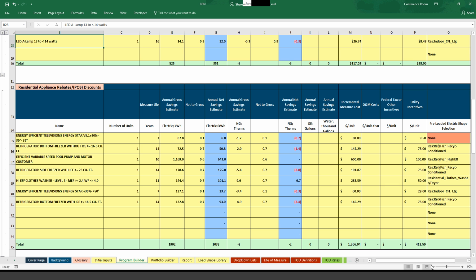We had to choose some, and so those are the ones that we settled upon, in part because a number of places do actually borrow values from the DEER, and that's the Database of Energy Efficiency Resources, I think, is what DEER stands for. A lot of states do have what's called a TRM, technical reference manual, that does specify incremental measure costs for common measures and so on. So if the numbers are not looking quite right and you're working in a different state, there might be a TRM, or there might be a TRM in an adjacent state that looks more like yours than California.